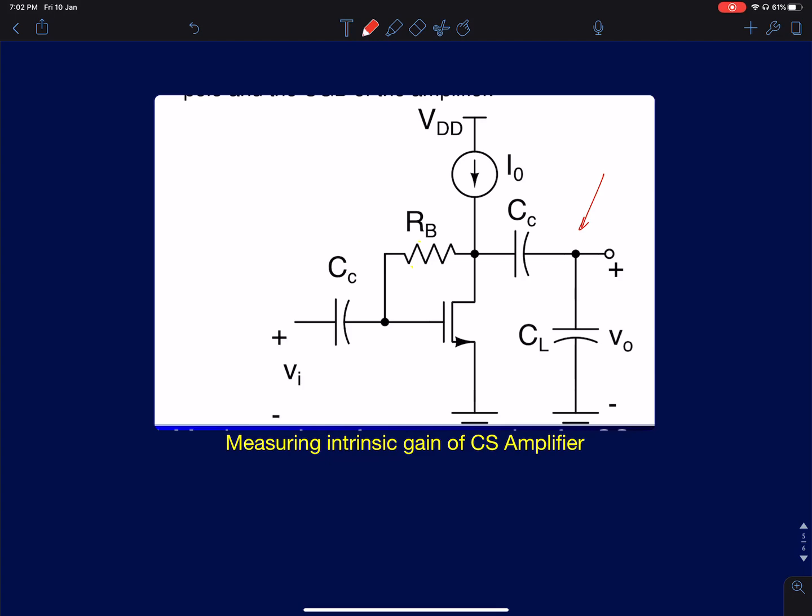So we don't really care about the capacitors here. What we do is connect, first, you have to configure the device in common source configuration. And in this setup, I'm doing a current source biasing. I need to fix the current and study the amplifier. The only difference is you need to connect a set resistance between the drain and gate terminals.